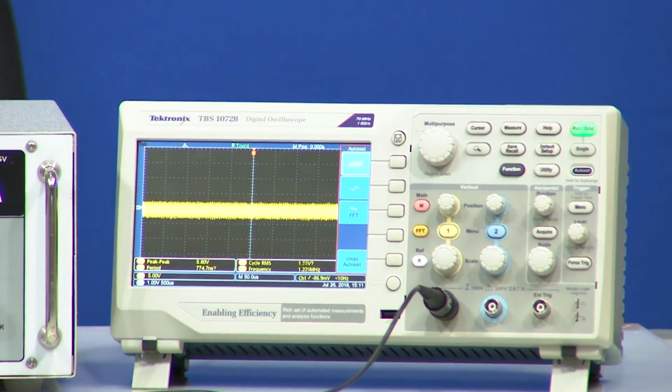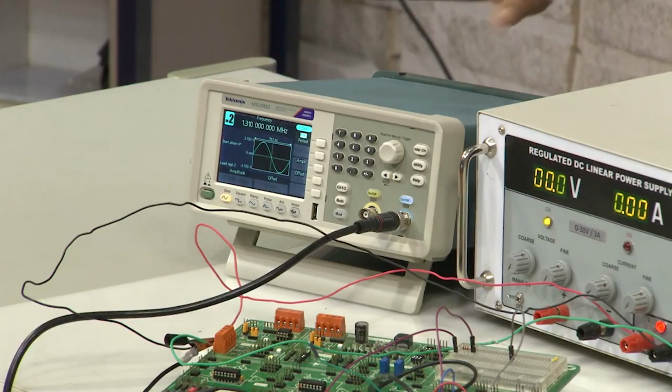Let us now compare both the circuits. Around 1 or 1.2 megahertz, we are seeing the output getting attenuated or distorted. Our first circuit had a gain of 2.2, our second circuit had a gain of 1. So the gain ratio between the two circuits is around 2.2. Accordingly, our first circuit had a frequency range of around 400 to 500 kilohertz, and our second circuit has a range of around 1.1 to 1.2 megahertz.